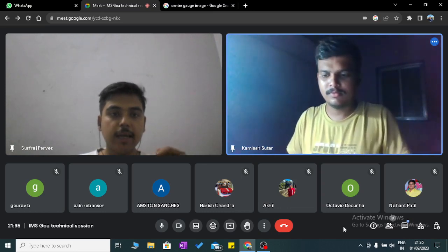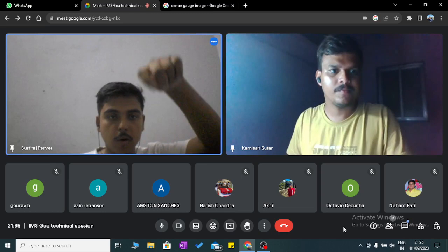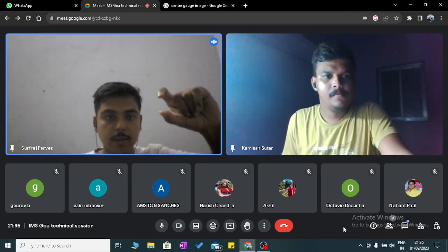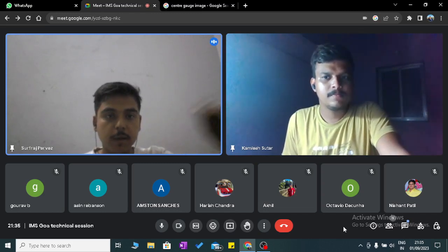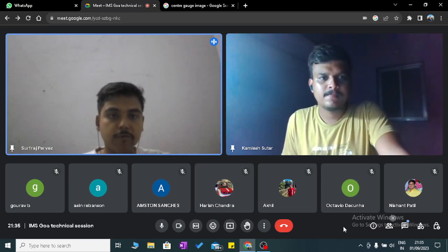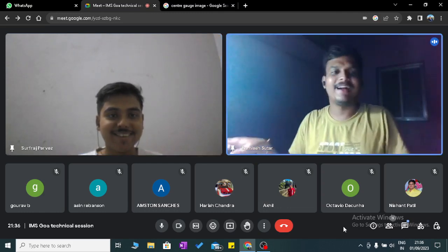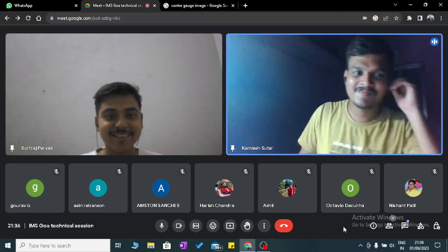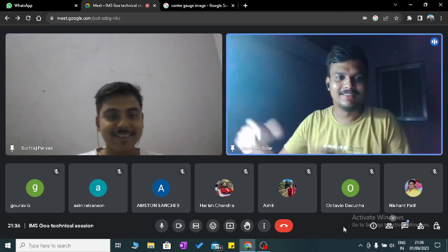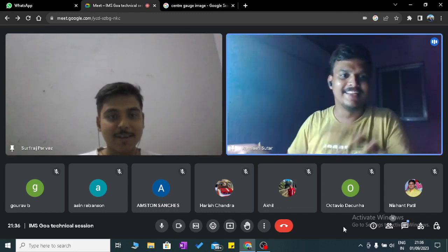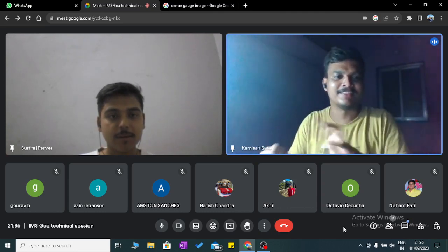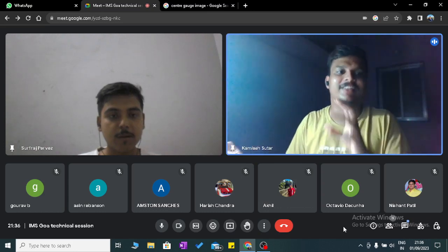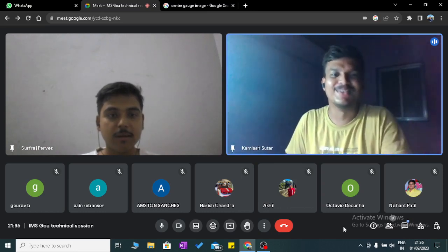Have you used the scale? We put the scale at all the ends of the chuck and measure the distance in mm, like 6 mm, 7 mm, and we count in all four different chucks. Have you done it? No, this is what I did in my engineering college. Actually, I was taught by the instructor rather than the teacher. It was a layman method: tap it, adjust it, give it a spin and see if it is centered properly.